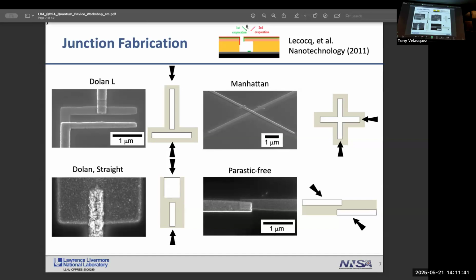In the first example here, which is quite conventional, you just deposit aluminum down one of these channels and then tilt the substrate. I hope it's roughly clear, but in each of these cases, the arrows are showing deposition at a tilted angle relative to the substrate to form these shadow structures.